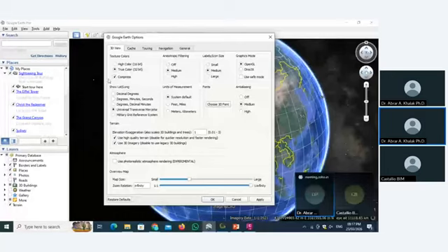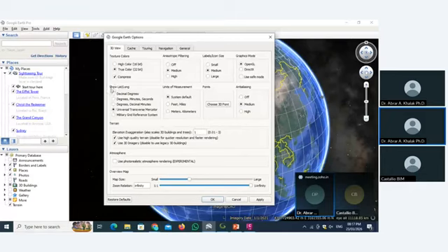Manage all our data, to manage all our terrain surface in a proper way. Okay, so what we do, we open this pop-up and select this latitude longitude tab, and here we have to select this Universal Transverse Mercator. In short, I call it UTM throughout the lecture. So you have to remember the full form of UTM, Universal Transverse Mercator.